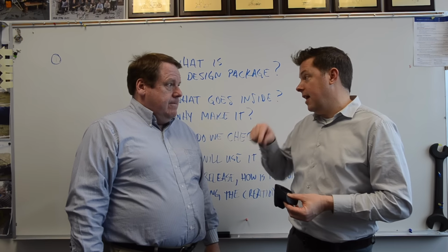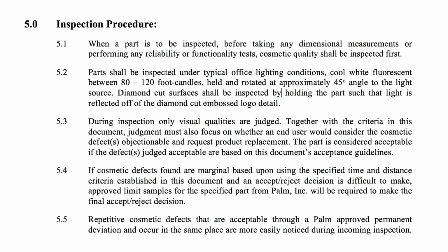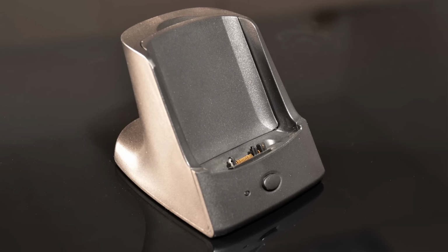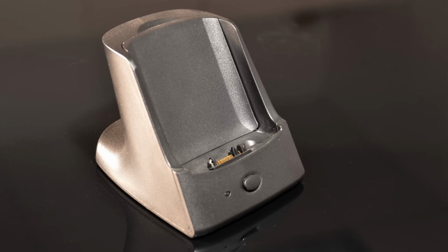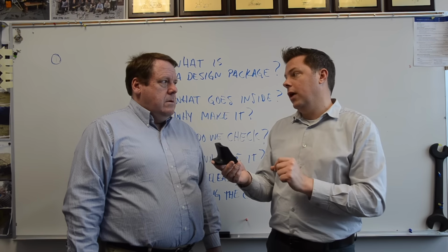But let me add the test on top of that, okay? So it turns out that for this cosmetic requirement, there is also a test associated with it. And it said at 36 inches on primary surface, you will see no blush mark larger than 1 millimeter or something like this, and you will not see more than 2 blush marks of 1 millimeter size within 1 square inch.